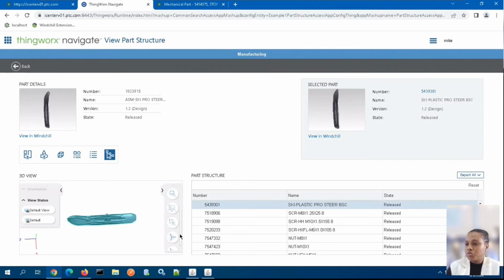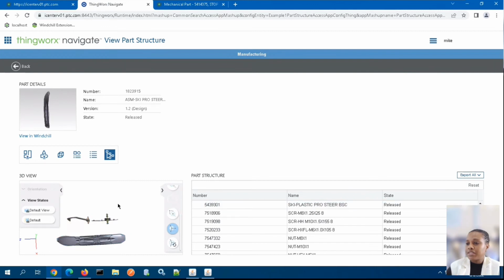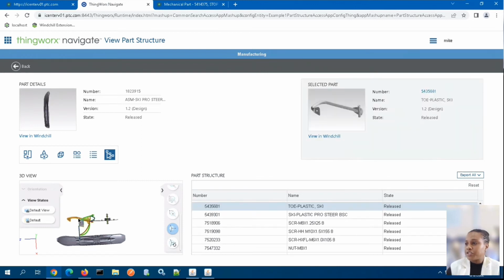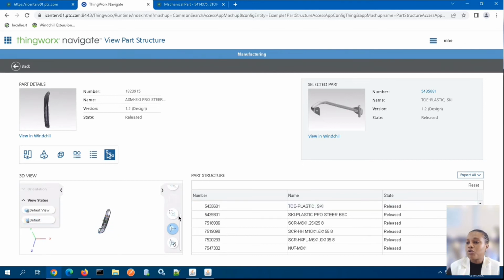And what you can also do, as I have said that we've got this part dragger, the minute you click that, you have the ability of splitting all the parts from that model. And the minute that you click on that particular part, it will reflect on the top right corner by using the transform options. And then by just a single click, it will put everything back together.